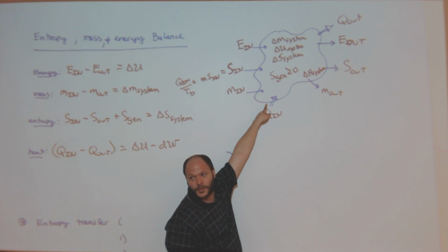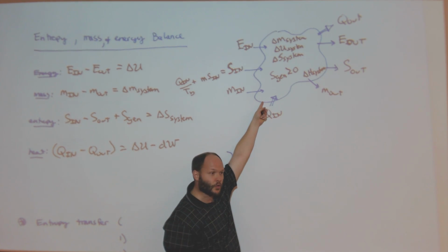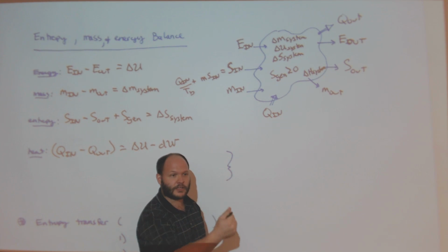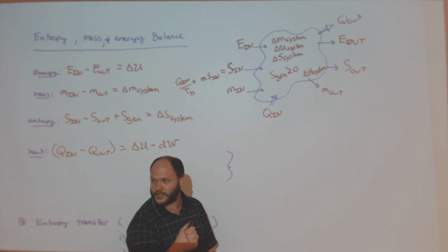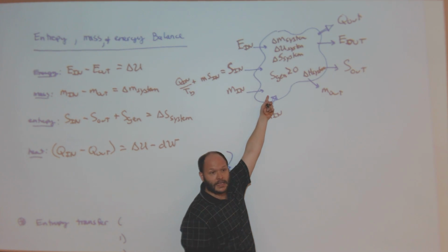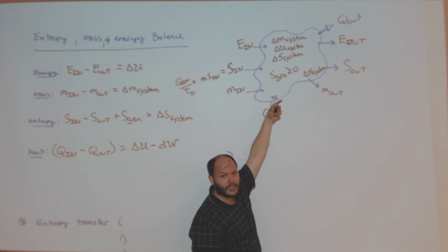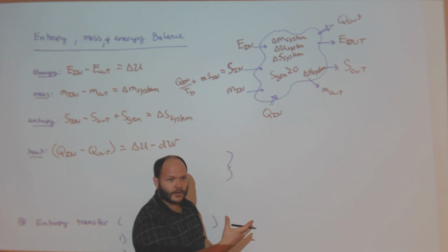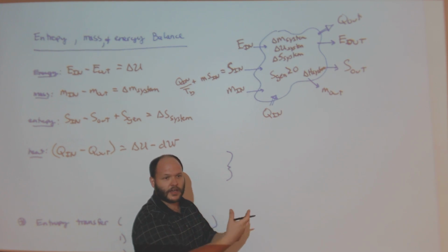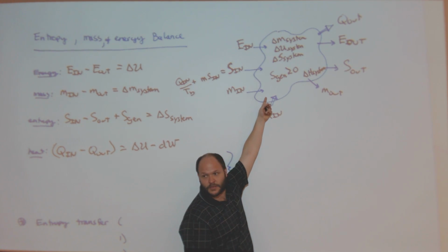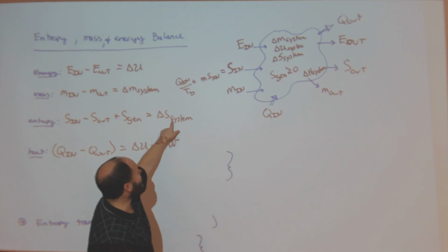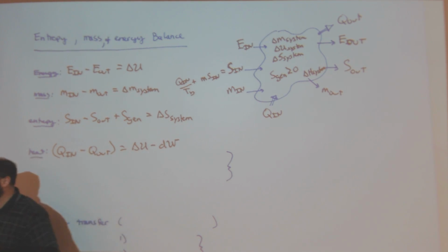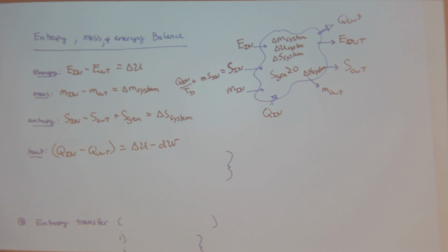Then I know the wall thickness, whatever it might be. I calculate the total mass of my stainless steel wall. I know its temperature and pressure. I calculate the total entropy of my container wall. Then I have a gas. I know its volume. I can give you the density. I can just tell you the total mass inside. You look up air at a given temperature and pressure. I can calculate the total entropy within. So then this is delta S of the system, delta S between two states, state 2 and state 1.